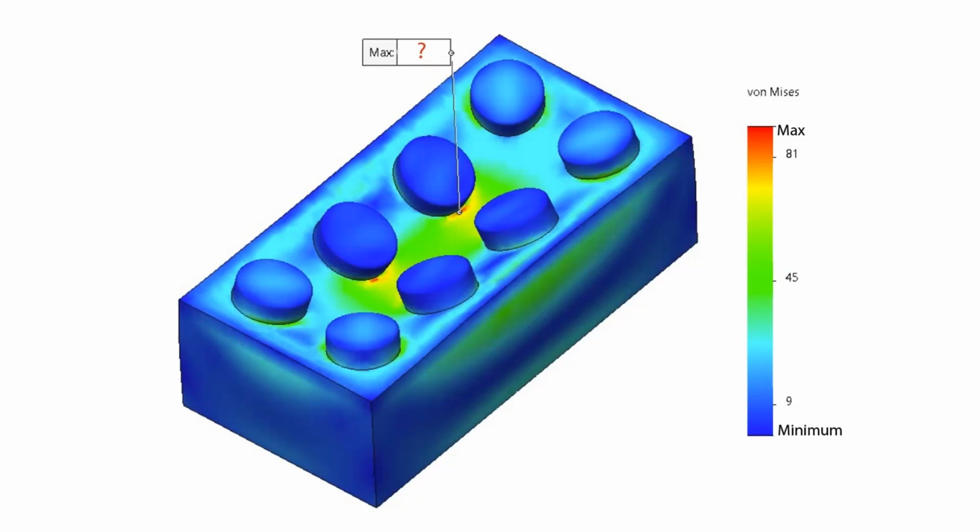We constructed a reference plane on top of the elliptical deformation, and because the stress close to the center was causing the studs in the middle to deform only on one axis, which we describe as the major axis of the formed ellipse, we relied on the major and minor axis considerations of the ellipse formed. We considered the ellipse's minor axis, which led us to an accurate value of about 2.4 for the radius of the stud.